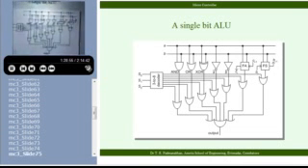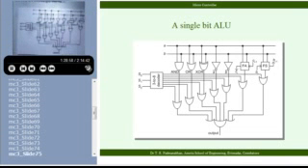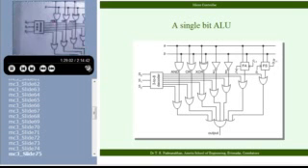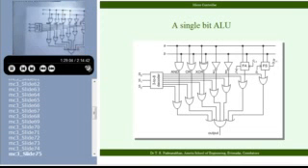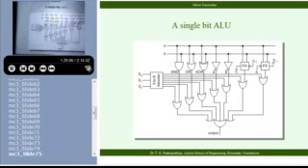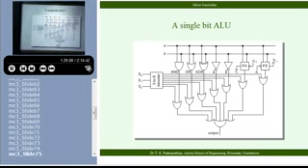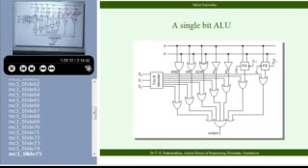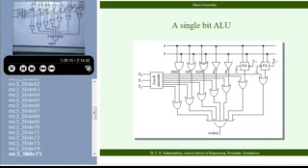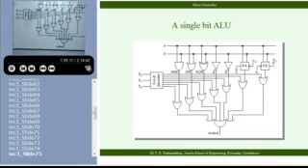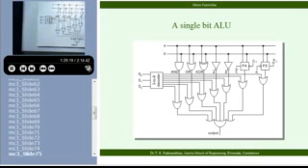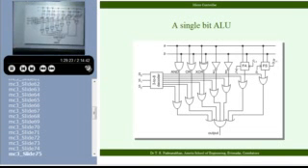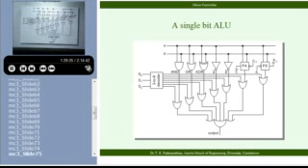I have a 3 to 8 decoder. With 3 bits, I select any one of these functions I want. I steer that to the output side. That single output bit is what you want. What I am saying is, with only 2 input bits and 1 output bit, I am taking a lot of effort to tell you that you can generate 1 output bit. But the point is it has got an identity. The identity is whether it's an AND operation, OR operation, whatever operation you want, the corresponding one you have got here.